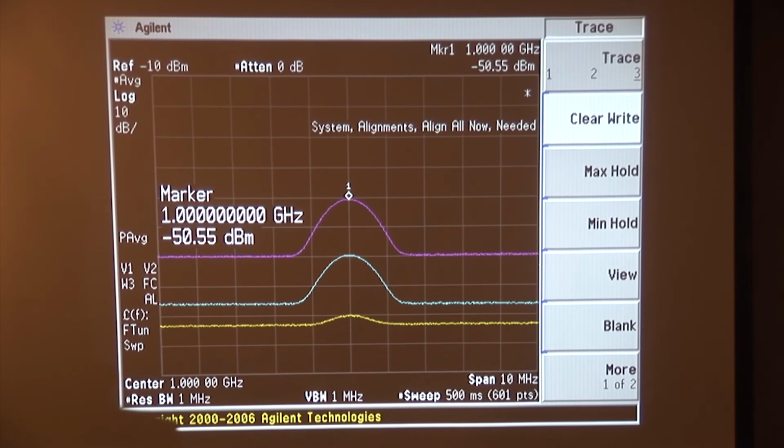As I said before, suppose that some guy bought this second amplifier, and you go, gosh darn it, it's got too much gain. Guess we're going to have to buy another amplifier. No, you don't. You don't need to buy another amplifier. All we need to do now is put that attenuator in between the amplifier and the front end. Now, we could go through the math and get the exact correct attenuator value, but why bother? We can do it this way. What we'd like to do is bring this down about 15, give or take, 15 dB right here.